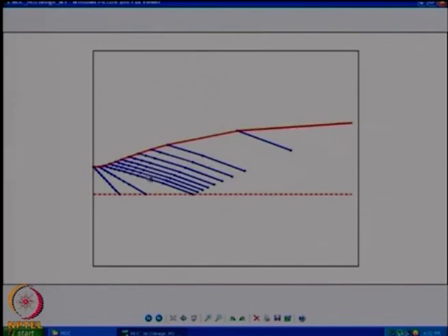By the way, the Mach angle in these regions will not be sin inverse 1 by 3. Only after this last line from the expanding circle will it be Mach 3. This is the last line where it is not Mach 3. Downstream of that everywhere it is Mach 3, theta equal to 0. This is what we were discussing before. So it just comes out to be that.